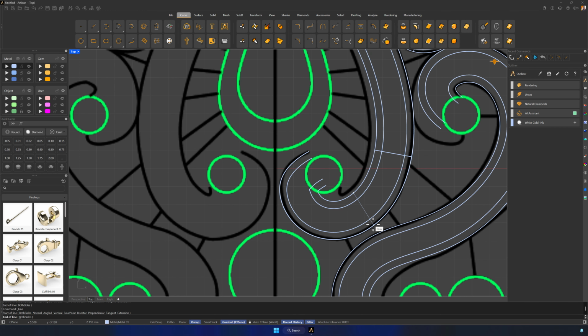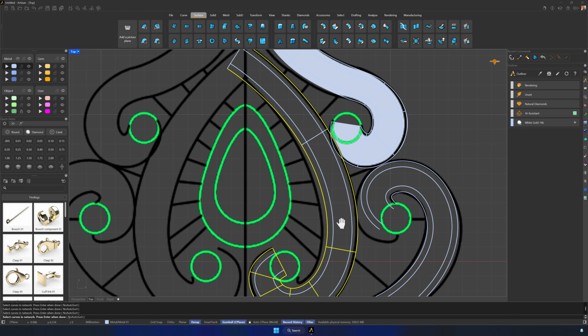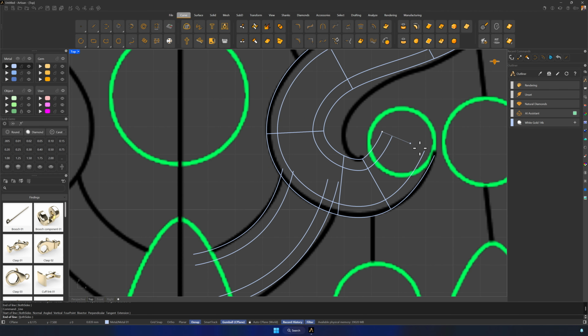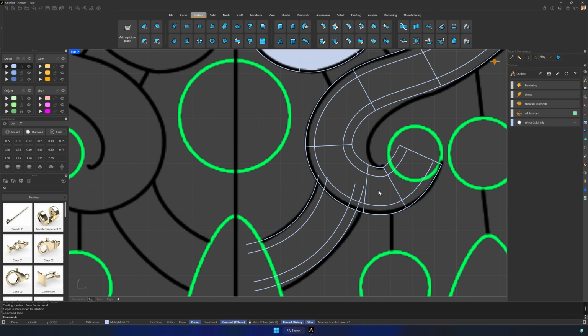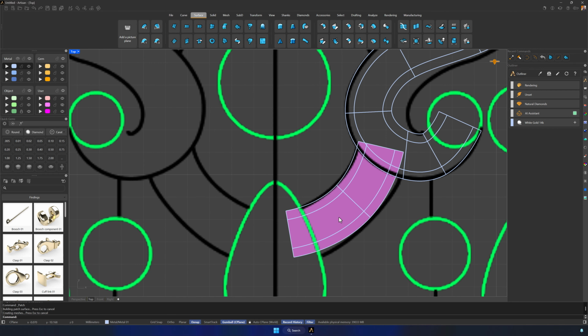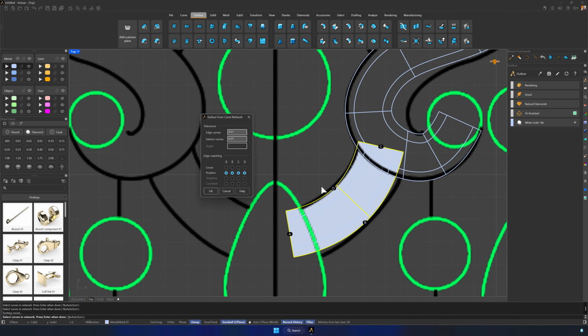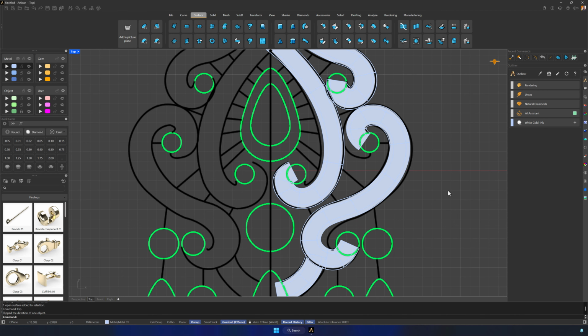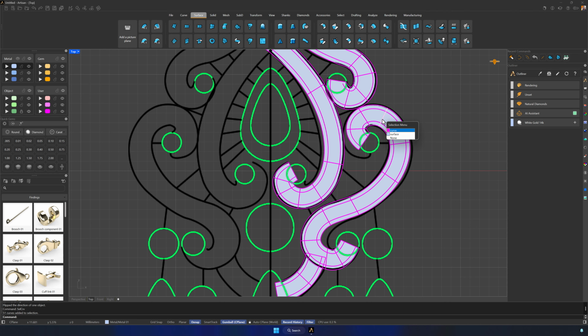Once all the curves are ready, we repeat the same workflow. There are many ways to build this model. We could use profiles, lofts, or networks. Each person should find the method that best fits their workflow. If the surface appears inverted, like in this case, we can simply apply a flip to fix it. Even so, if we check the topology and notice it's not correct, it usually means we're missing a reference line. So we redo it, add the missing line, and generate the surface again.